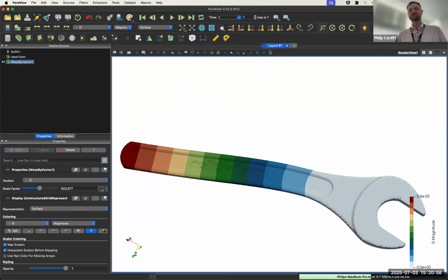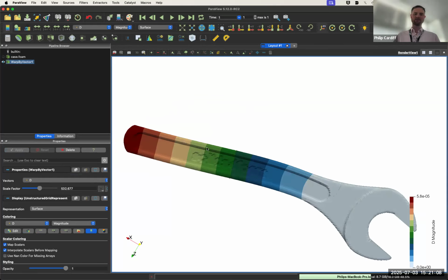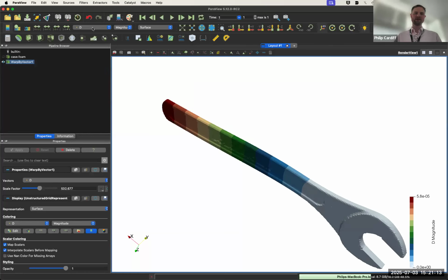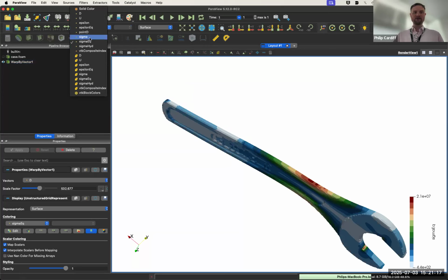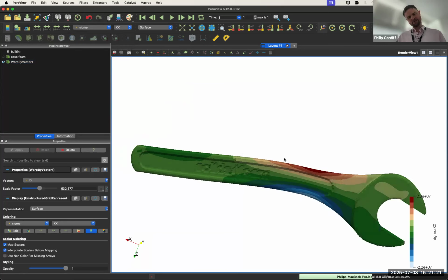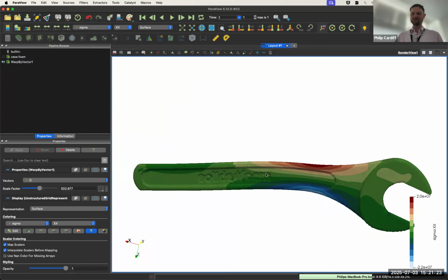And this will be like, if I use Abaqus a lot, the commercial FEA software, it will check the bounding box and the magnitude of displacement and then scale it to be proportional to that. So you can see it bends around like this, and then you can look at, this is half the geometry. So if you want, you could reflect it to see the full geometry. And then you can look at the stress tensor. So the stress tensor, X, Y, Z, etc. So if that's X in that direction, so if you did solid mechanics courses, then you know that in bending, you get tension on top and compression on the bottom. So tension, compression.